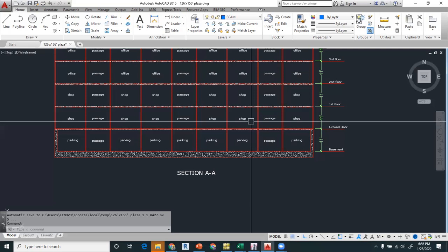So that's why it's giving me more reinforcement at the lift location. You have seen that the third layer was not at the other locations. It was near the lift locations. So you can give top 2 layers and increase the diameter of the bar, and you can increase the number of layers by decreasing the diameter of the bar.